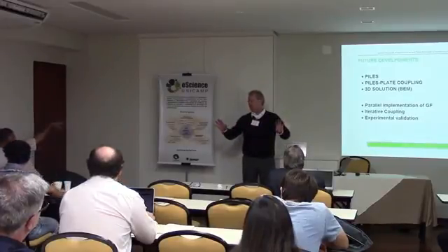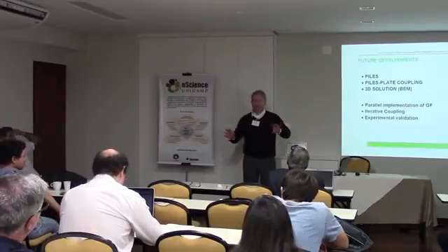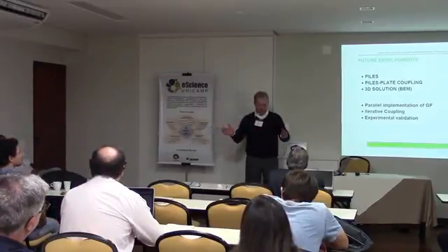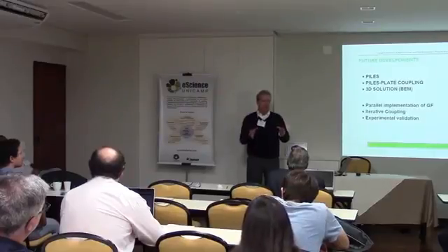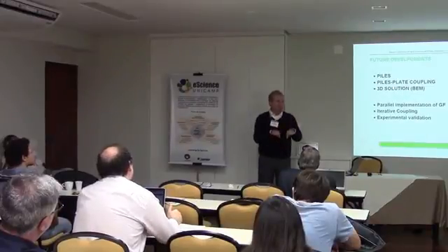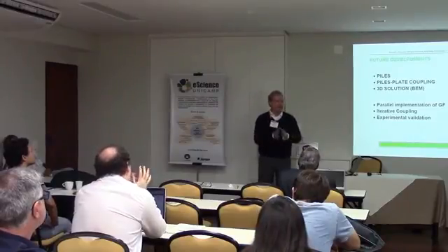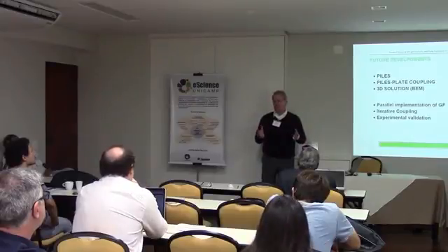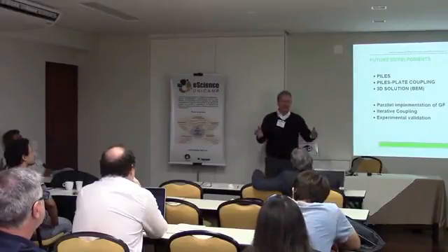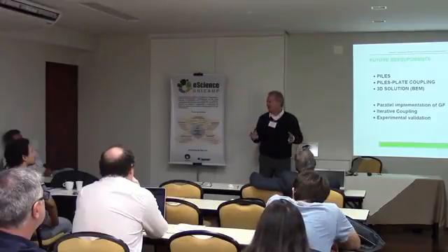I know the results for the transient case, so for all frequencies it will not be the case. But when you excite from outside, you have an incoming field, and with piles the whole system is strongly coupled to the source, so the amplitude is large. Now, if you excite the foundation, it's the opposite. The system coupled with the piles will damp more rapidly than the one that is not coupled. So there's a trade-off, depending on where your excitation is coming from. If your excitation comes from outside, you don't wish to have the piles. If it comes from inside, you wish to have the piles.